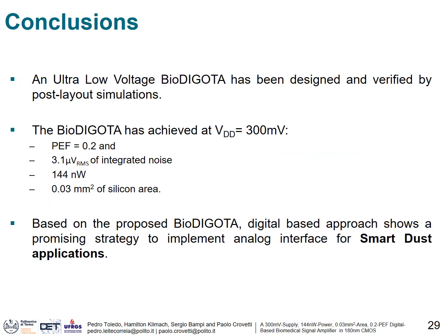Conclusions. An ultra-low voltage BioDIGOTA has been designed and verified by post-layout simulation. The proposed BioDIGOTA has achieved, at VDD equal to 300 mV, a power efficiency factor of 0.2 and 3.1 microvolts RMS of integrated noise.